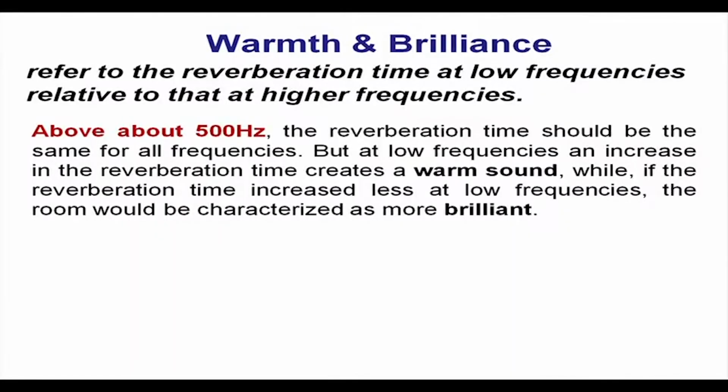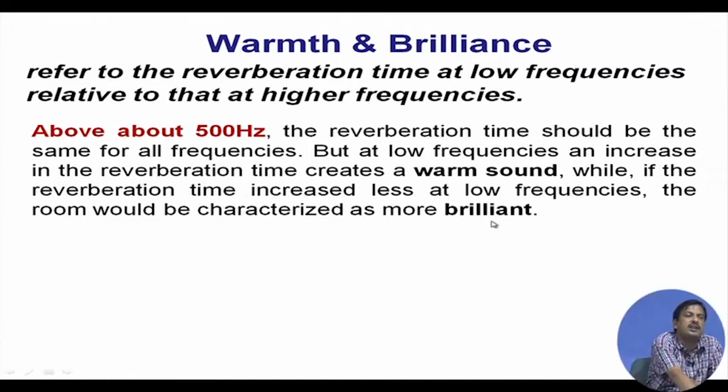Then this parameter refers to the reverberation time at low frequency relative to that at higher frequency. That means, above 500 Hz the reverberation time should be small for all frequencies, but at low frequency an increase in the reverberation time creates a warm sound, while if the reverberation time increase is less at low frequency, it creates a brilliant sound. Okay. So, this is the definition of warmth and brilliance.